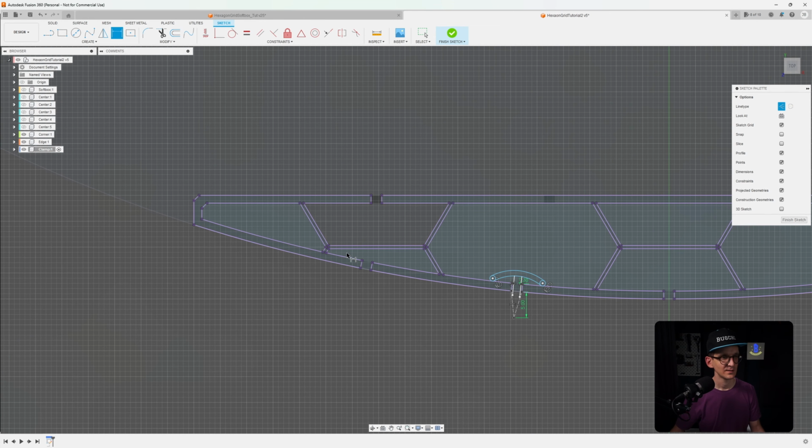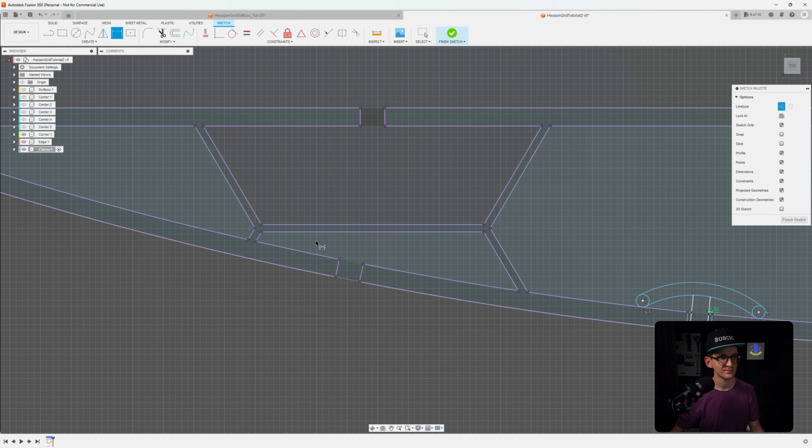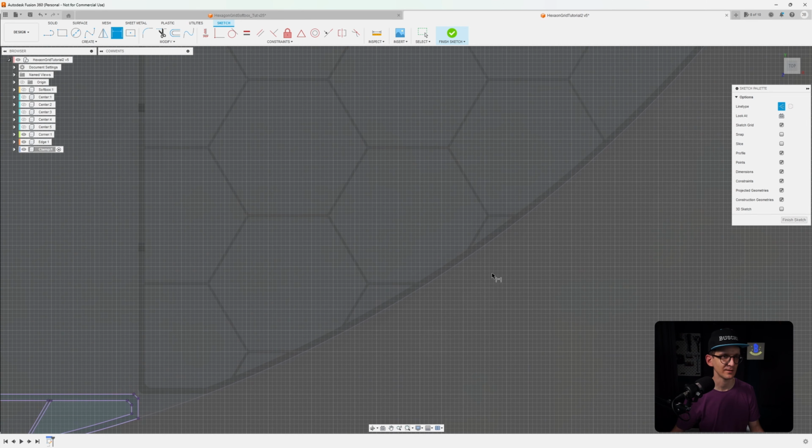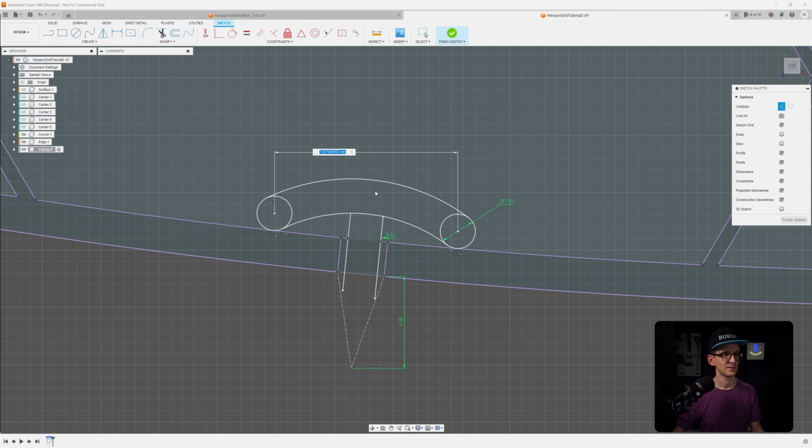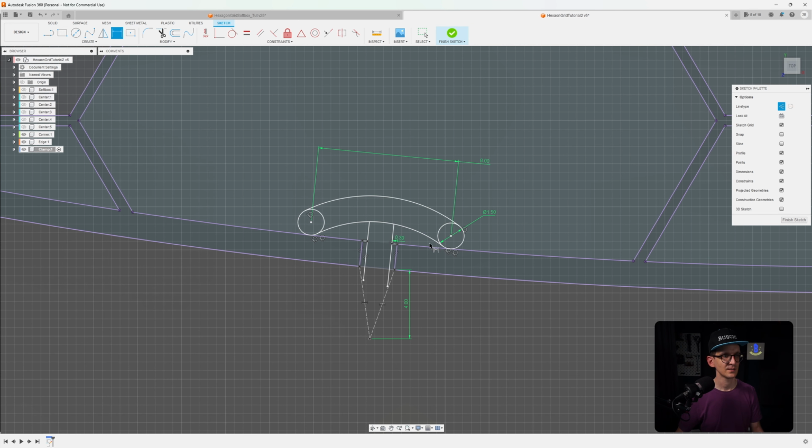So the arc is a bit wider, which we can see is going to be a problem here. Maybe all the other pieces should be fine, I guess. Maybe let's make it 4. All right. Then also we can constrain the diameter here, which I would like to have 1.5 millimeters. And you can always move it around to see where the freedom still is. We need to define how far apart those two points should be. And actually this is a bad way of doing it because we're not following the geometry. So it would be better this way. Maybe 8 millimeters. And now you can see that it is fully defined. Everything is fine. Oops. 8. I wanted 8. Thank you.